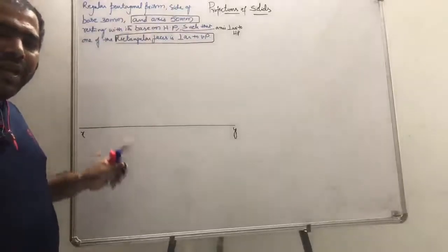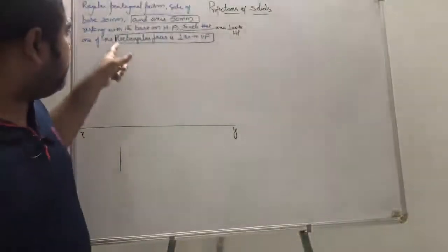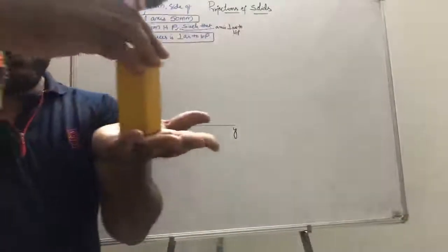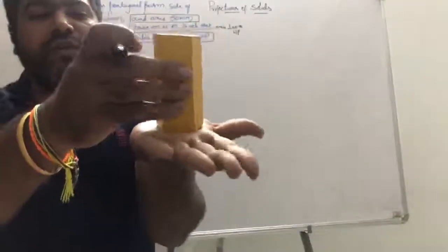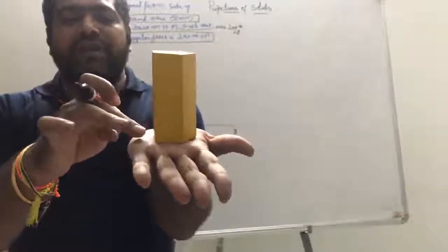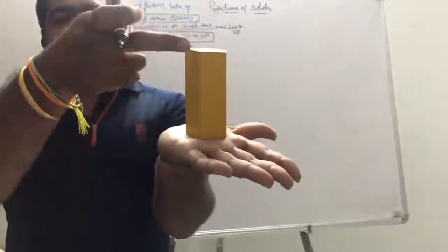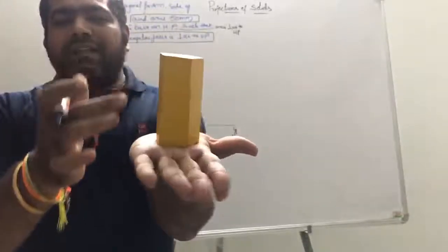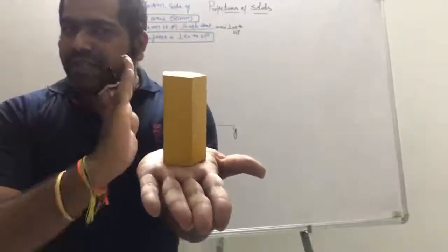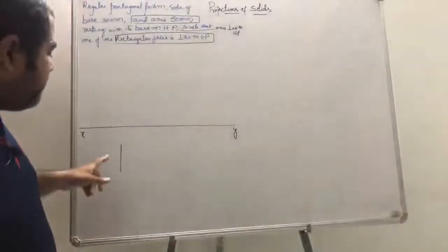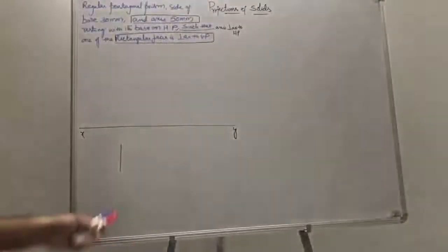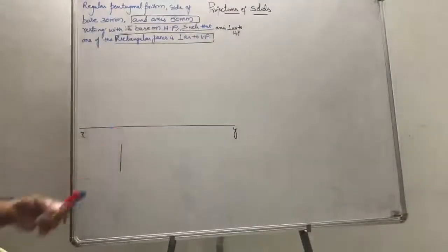While you put your edge like this, it means your rectangular face is perpendicular to VP. Let us see here. If I put like this, this edge is going to be perpendicular to XY, which means if you join this edge and this edge, you obtain a rectangular face. This rectangular face is perpendicular to VP. Okay. So furthermore, always when you start the problem as an edge resting problem, you just draw that the edge must be perpendicular to XY.